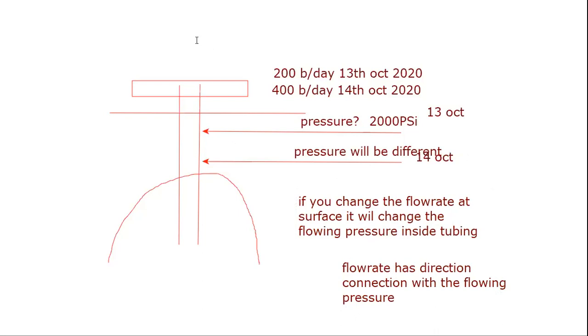Now, IPR is the term which is connecting both of them. Inflow performance relationship is the graph between the flow rate versus the pressure, and it tells us at this flow rate, what will be the pressure. Now let me show you some IPR.